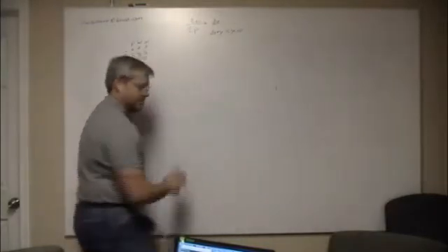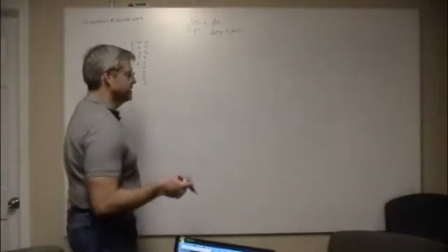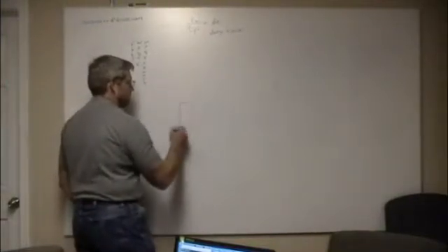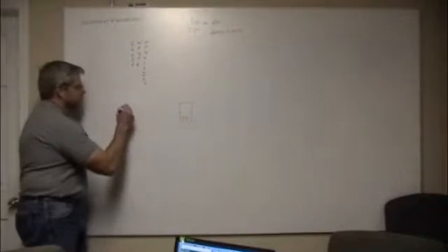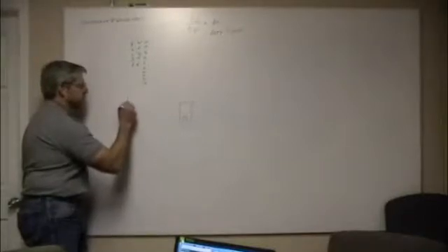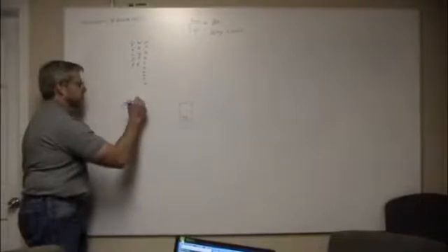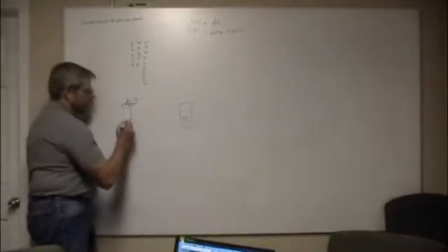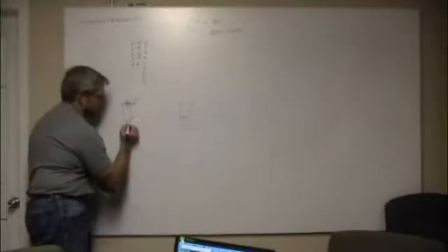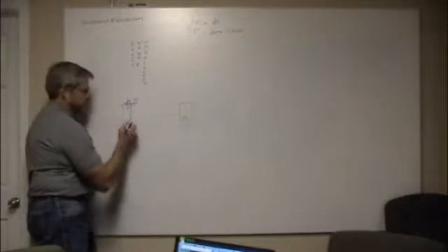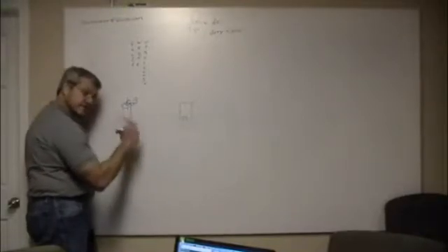So we want a PWM. The other reason we want a PWM is because of servo motors. The two main reasons you want a PWM are because of servo motors. We'll get into a third one here in just a minute, but I didn't do anything with that. A servo motor, the way they work, generally speaking, is you've got a DC motor, the shaft that comes up, and most often there's gears. There's several gears, stacked gears that come back. I've got one there on the table. And somehow, maybe there's a potentiometer down here, and so it's a DC motor.